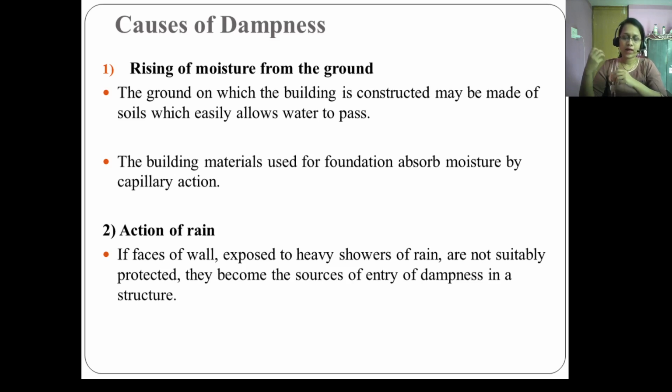If the balconies and chhaja protections do not have a proper outward slope, water will accumulate, right? Water will accumulate on this and could ultimately enter the walls through their junction. This moisture travel will completely deface the interior decoration of the walls.